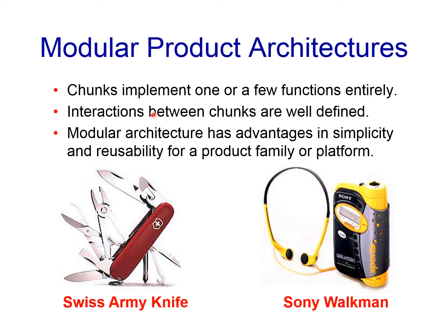Finally, modular architectures have advantages in simplicity and reusability for a product family or platform. It allows us to have product families without having a tremendous amount of production complexity and cost. What are some of the disadvantages then for a modular design? Perhaps they tend to be bulky, maybe increased cost because you're designing each module separately to perform a specific function. Any other disadvantages that come to mind?